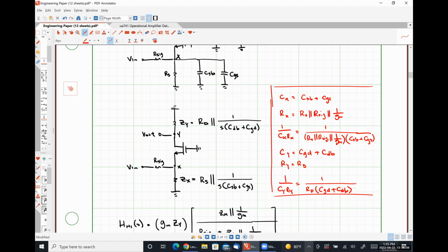Effectively, I'm going to give you almost exactly what we did in the derivation, except with a BJT, and ask you to figure out what the poles and zeros are. It's going to be effectively the same thing, except you're going to have one more small addition to the transfer function because R pi isn't infinite. You'll have another small thing in brackets for the transfer function.